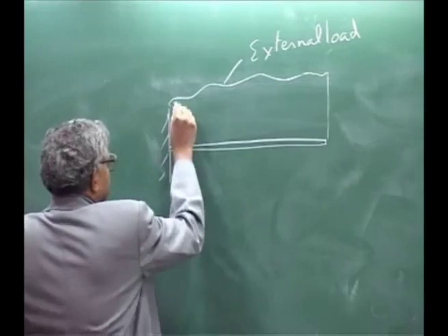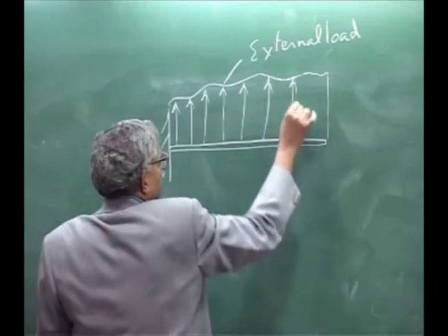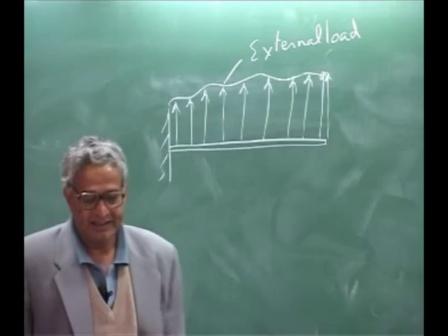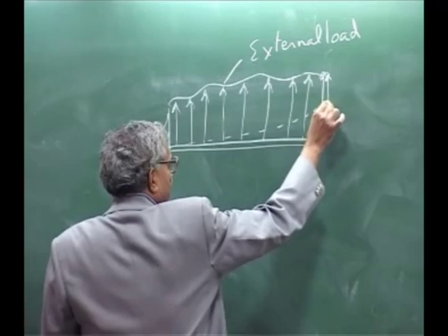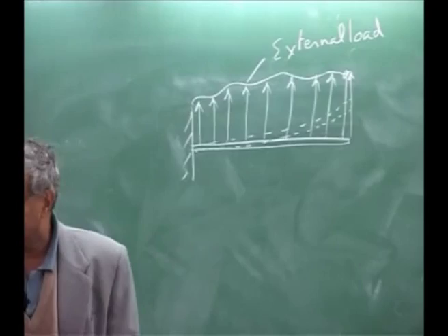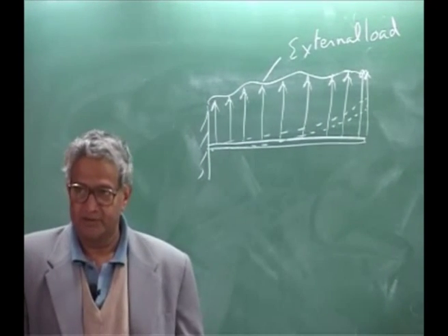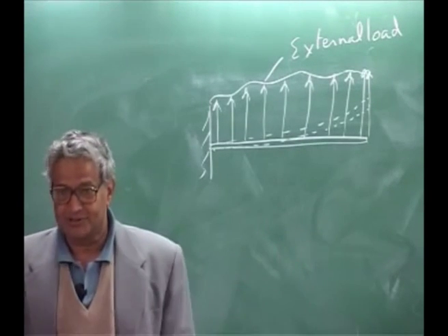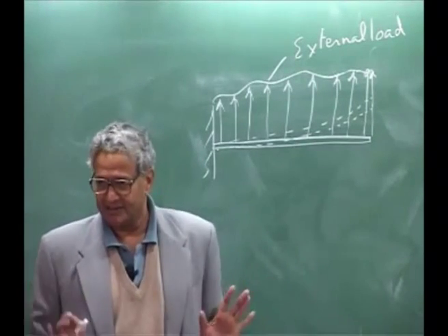This is distributed. Okay. All right. And this is going to deform. This will have some deformation. Now for this we need to get, because this is what our realistic case is. You have a distributed load, you want to know how the wing deforms under the action of a distributed load. Whether it is a bending or a tension. Here we take a bending case.